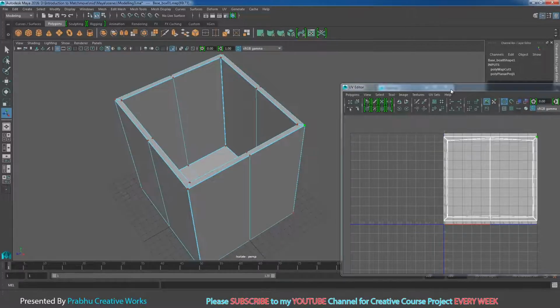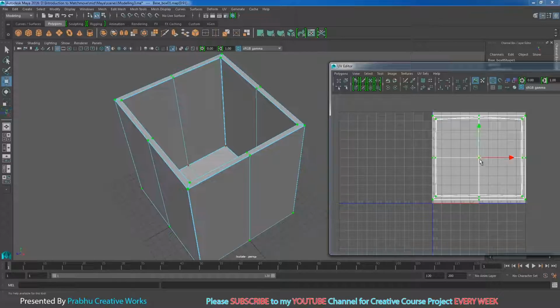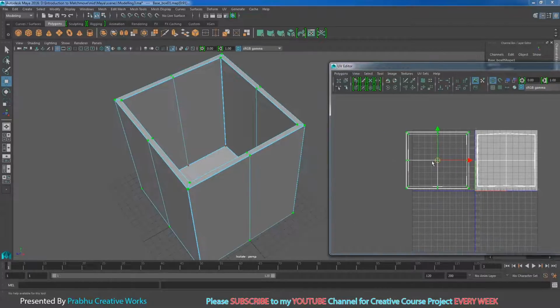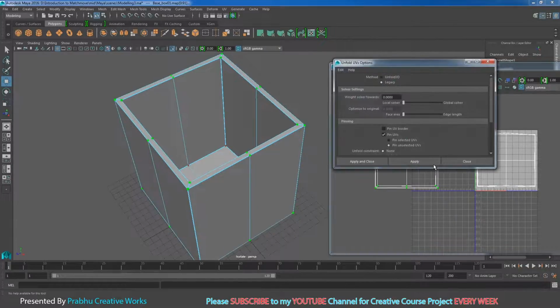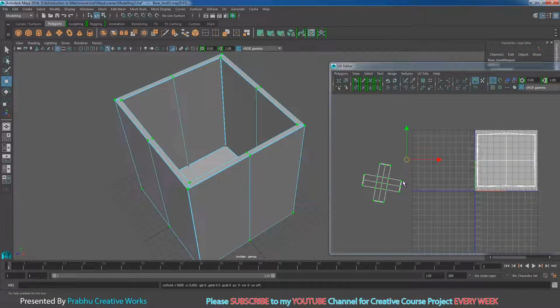Now go to the UV Editor, Control right click and choose UV shell. That means our outer UV will be selected. Press W and move it to this side like this. When your outer UV is fully selected, shift right click and choose the unfold option box. Here you want to choose legacy. By default it's set to unfold 3D; choose legacy and choose apply and close. That means our UV will split perfectly over here.